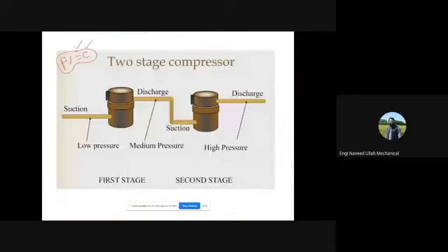process in a single cylinder or in a single stage, ठीक है, तो complete intercooling जो है ना आप नहीं कर सकते, so for that reason हमें चाहिए to make the process nearly isothermal, so for that reason you use the two stage or three stage compression process.